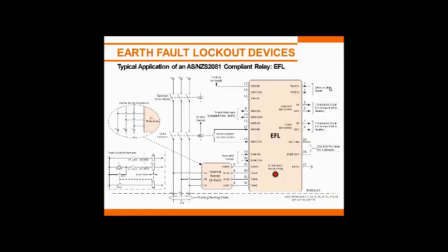Power supply, 24 volts AC/DC, keeping with our standard connection we're using these days. Trip indication for earth fault lockout coming out here, and one for frozen contactor there. The external reset, which is for the earth fault lockout. This relay also has an under voltage trip, but I'll ignore that at the moment. That can be used or not used. And then this gives you a little bit more about the circuit needed to set it up and run it, and get it operational so that it meets all the requirements of the standard.